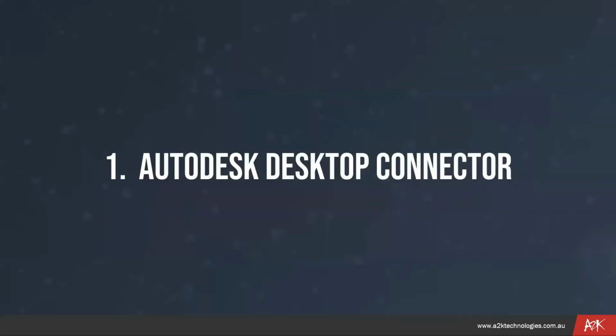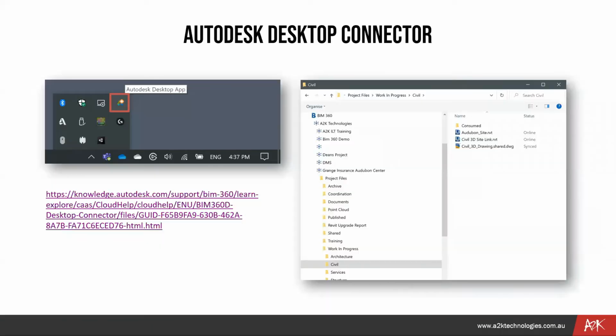Okay, so let's start with the Autodesk desktop connector. This is something that everybody who is using, in particular, BIM 360 should have installed. It gives you a locally accessible, syncable drive to the BIM 360 data that you have been added to those project spaces. There's a link there that you can use to go ahead and download it. We will provide this as a PDF after the presentation, or you can just simply do a Google search for the Autodesk desktop connector. It's not a requirement, but it certainly helps with having access to these files through these local drives.